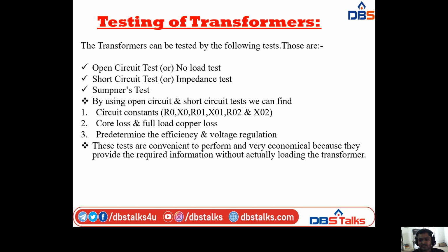So first is the open circuit test. This test is also called the no load test. And the second one is the short circuit test. This one is also called the impedance test. And the third one is Sumpner's test. And we have another one, that is the load test. But in our syllabus they didn't give this one, so I did not take that one.